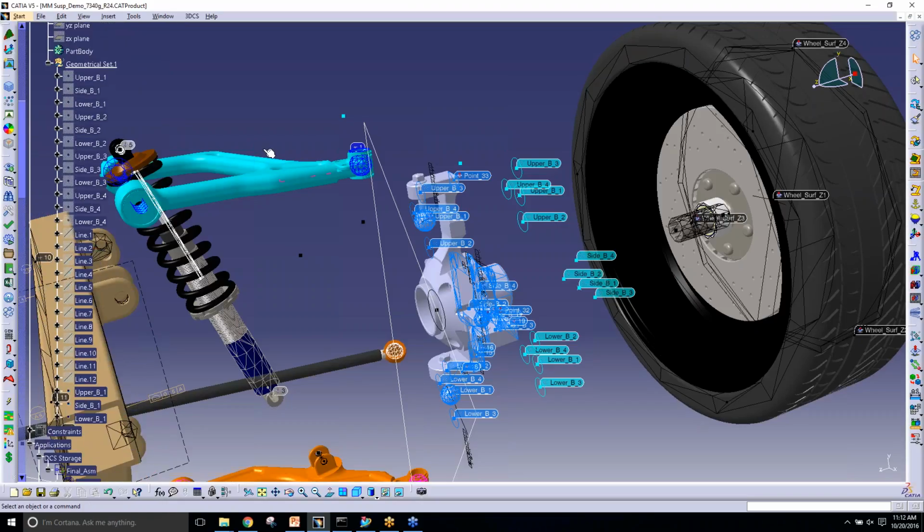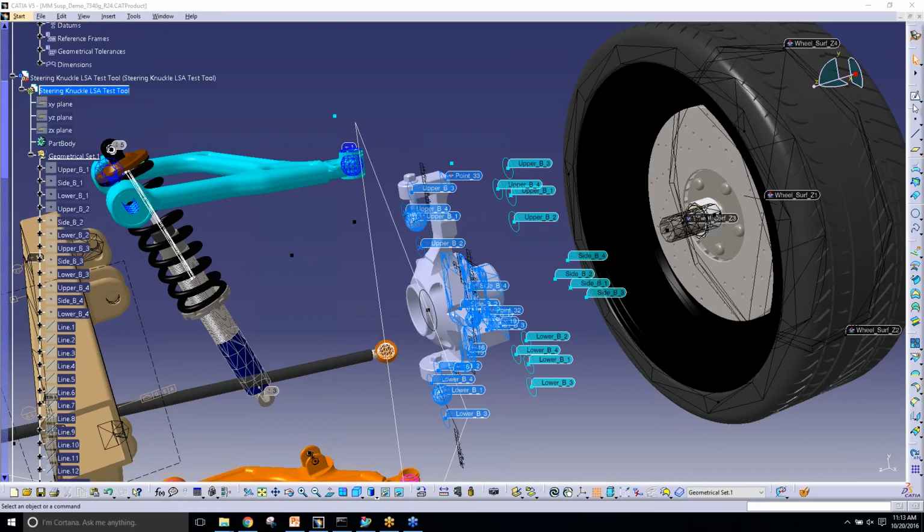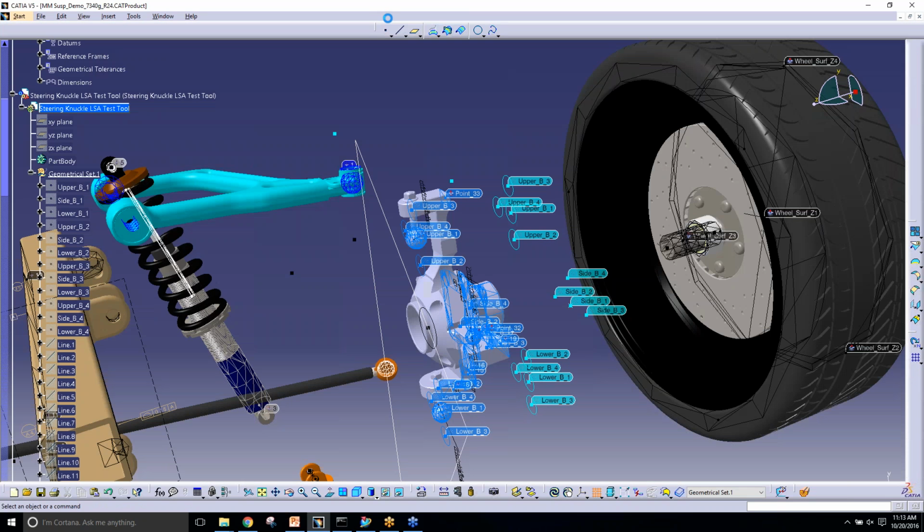So what you're saying is you can use CAD lines to model fixtures in your model. If you're doing an assembly, one of the great things about 3DCS is it allows you to simulate manufacturing processes, not just design. So we can actually show each assembly step with the fixtures. We can take a part, move it to a fixture, and then move that into an assembly, and show step by step, including fixtures and any variation or any processes the fixtures are involved with along the way. Yeah. And this is one method you can use to show those fixtures.